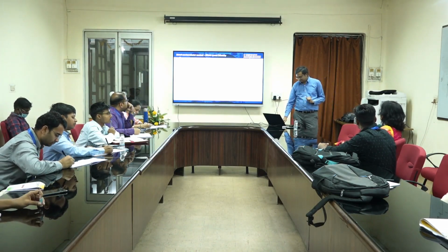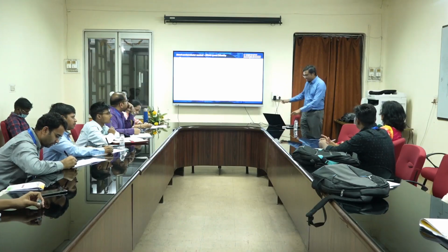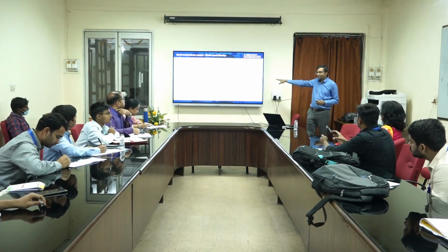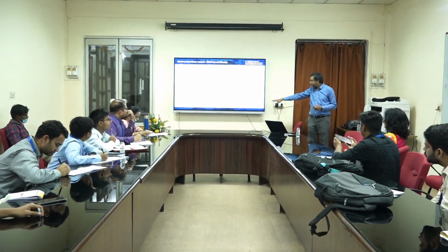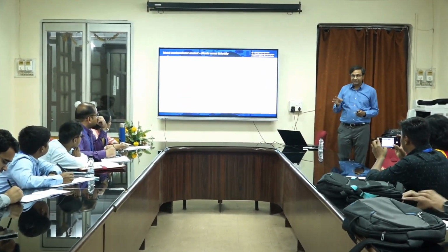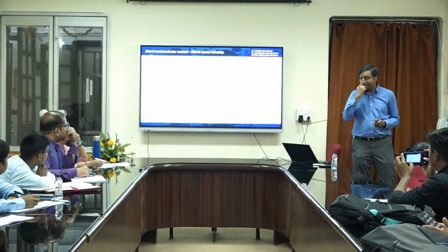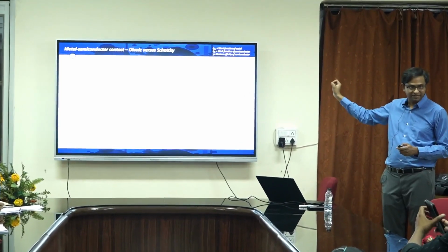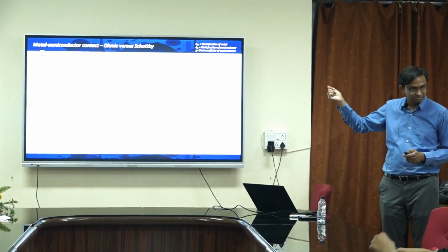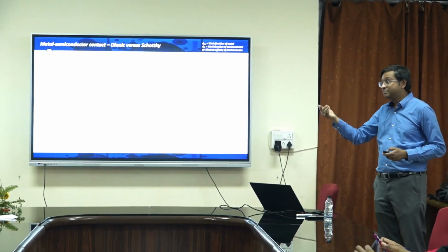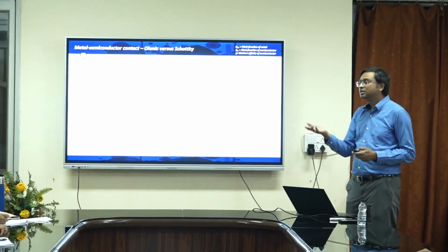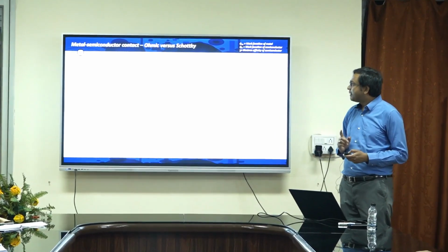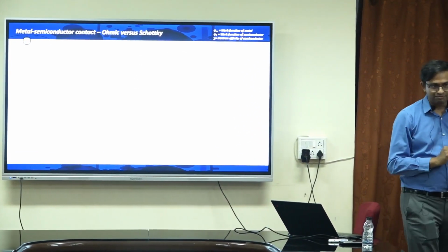So this is what happens for the N type, and then what we say is that the first one is a Schottky contact for an N type FET, and the second one is an ohmic contact for an N type FET. Because remember, we have to get to an ohmic contact, only then all those discussions that we had earlier today are valid. So therefore, for an N type material, you will choose a metal with low work function. Make sense? What happens if I change it to the P type material?